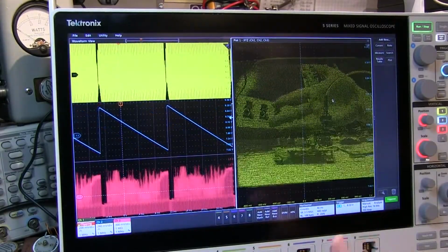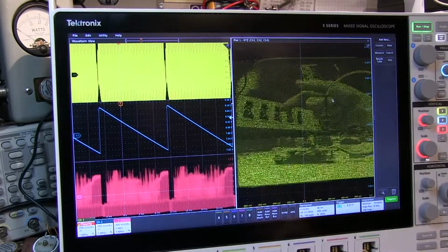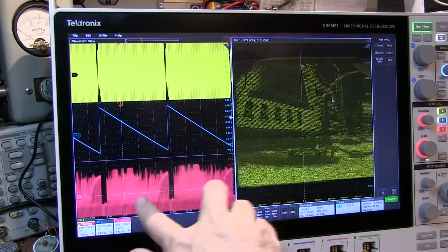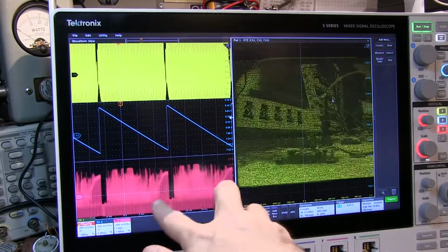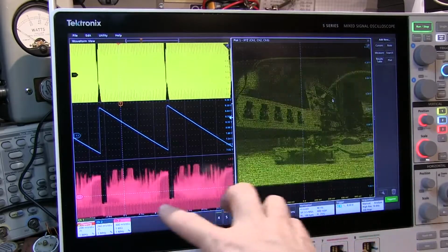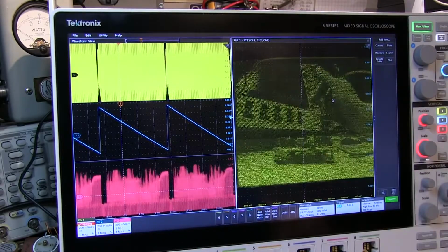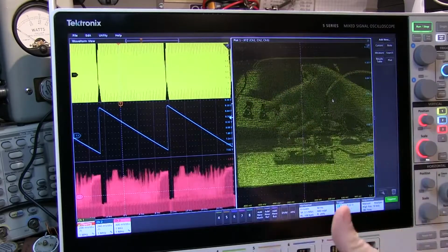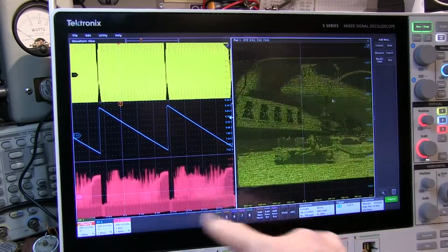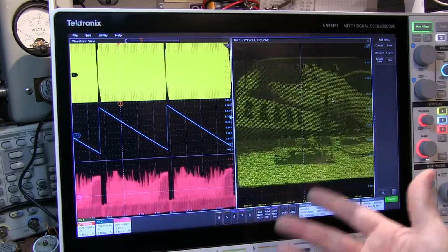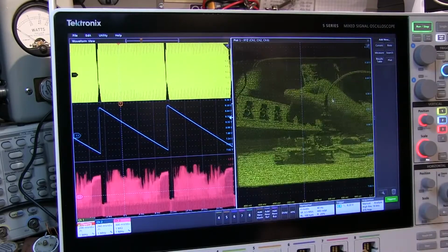Of course, the composite video that we're getting here is a little grainy, and that's because I've really only got 2 full video frames being shown, so we're not getting enough to fill in the display. But it gives me a nice lively update because we're only grabbing about 40 milliseconds worth of data, so I'm getting a new update about every 40 milliseconds here.